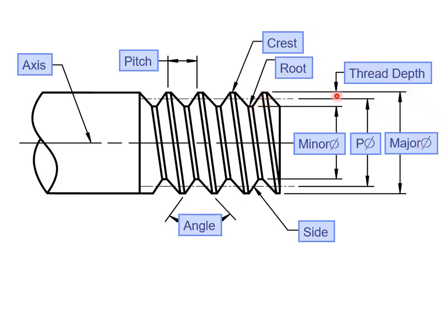Okay, here we have the major diameter, which is the distance from crest to crest. That's the major diameter. Minor diameter is from root to root. And the pitch diameter, it's not exactly in the middle or the average. It's where this line equals this line. So the depth of the tooth here and this length here equal each other, and you go to the opposite, and that'll give us our pitch diameter. The one that is important is the major diameter. Okay, and then we have the angle and the sidewall.